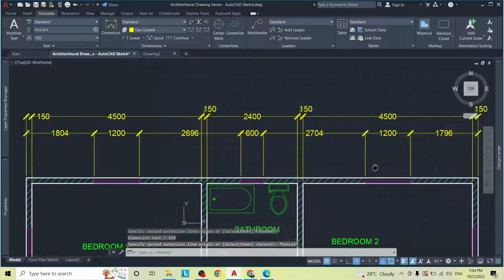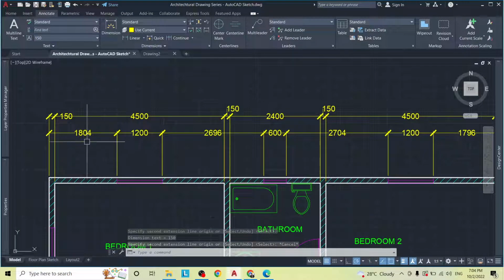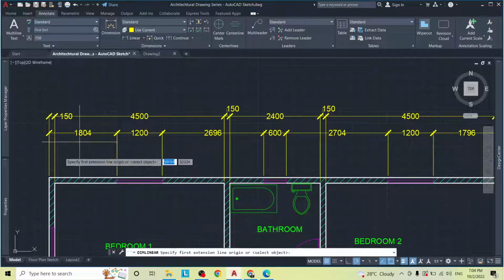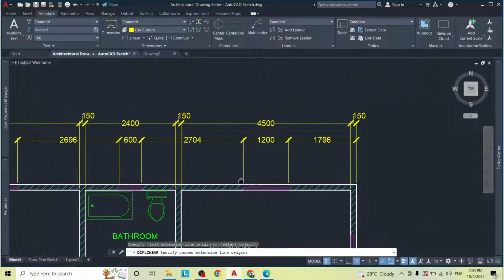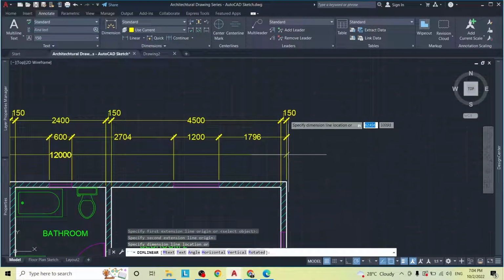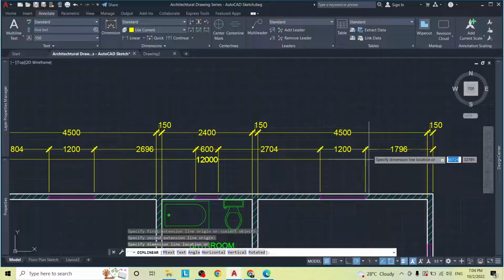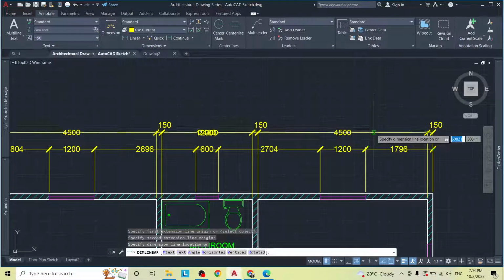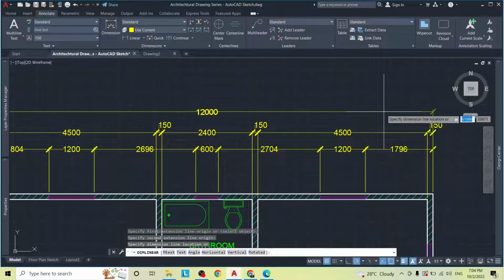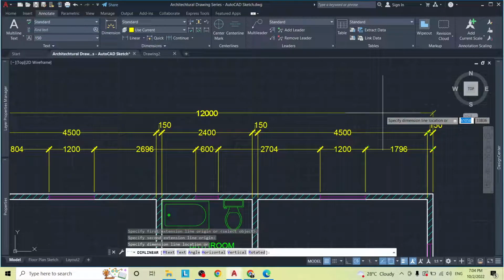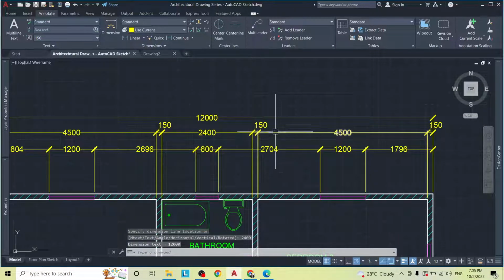And then finally, we're going to show the overall measurement of the entire side of the building. So we're going to add 600. We're going to go from one end straight to the other end, and so we have 1200 here. This one is added 600, that's 1800, and then we add another 600, that's 2400. So I hit 2400, I hit enter, and there we go.